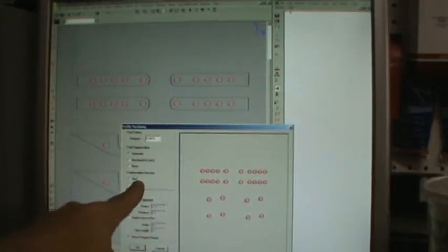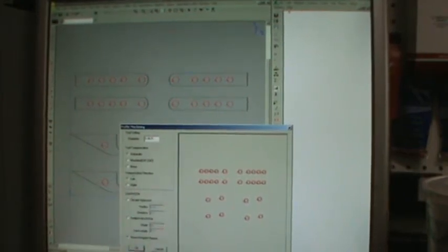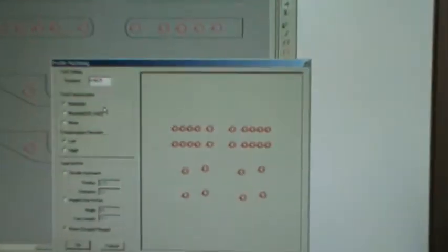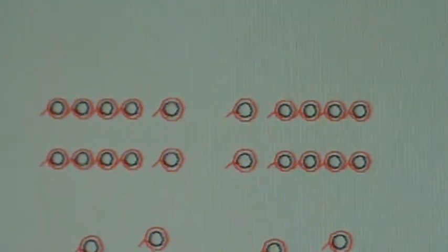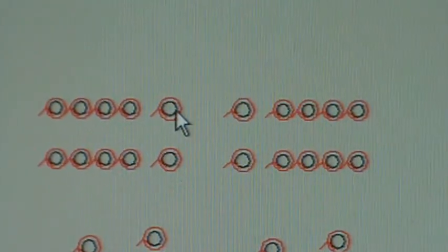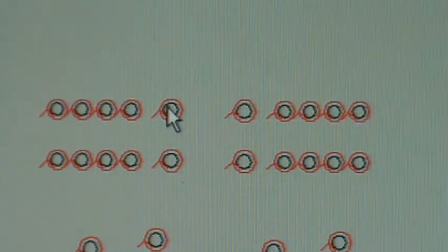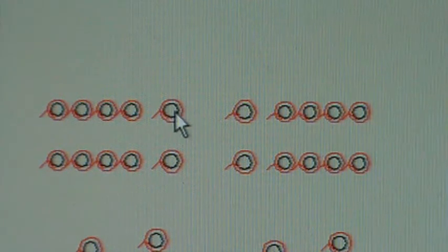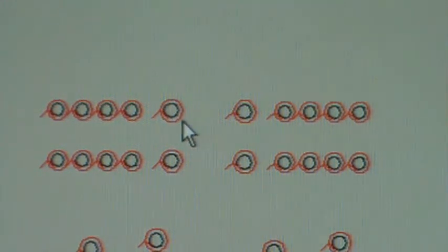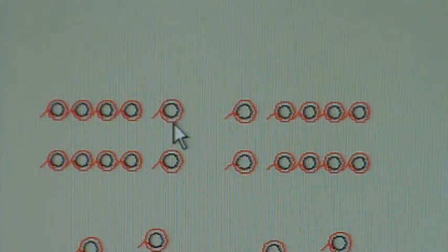And our compensation direction, the comment about leaving all of the arrows pointing the same direction when you select this stuff is, I'll zoom you in right here to where it's going to show this. What you can see is you have your actual hole. The black is what you actually want your part to be. The red is the center line of the cutter.